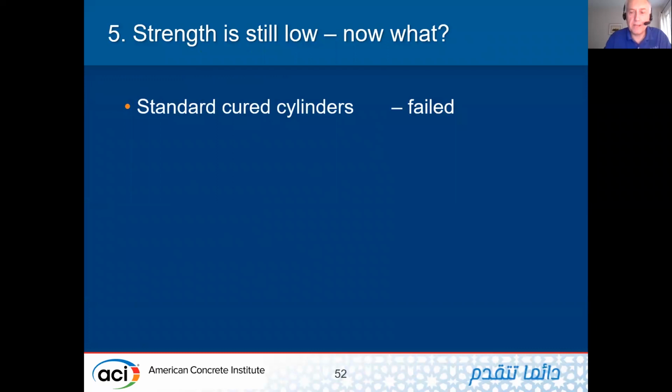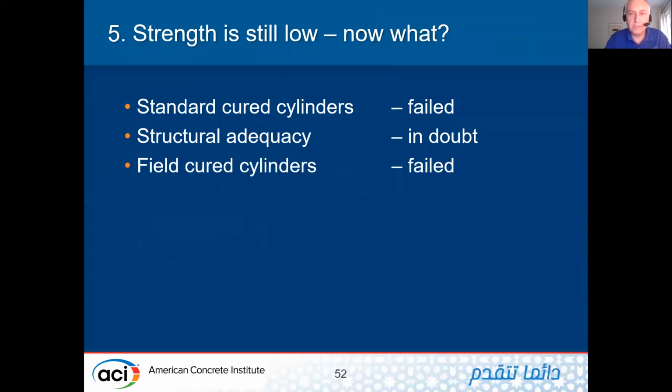Okay, so let's recap everything we talked about. Standard cured cylinders, let's say they failed, structural adequacy has been checked, it's still in doubt. You look at field cured cylinders, they failed.